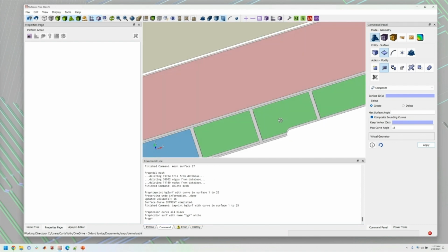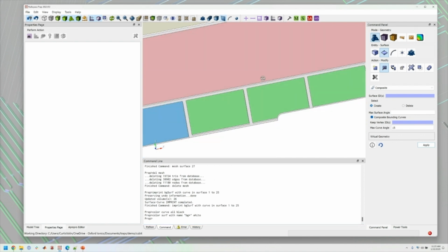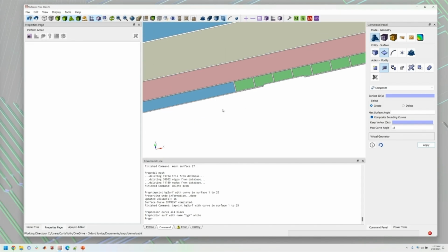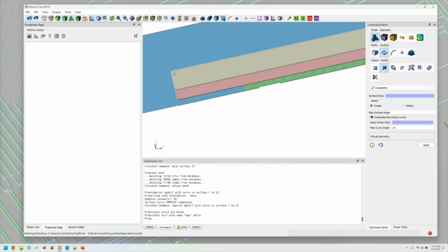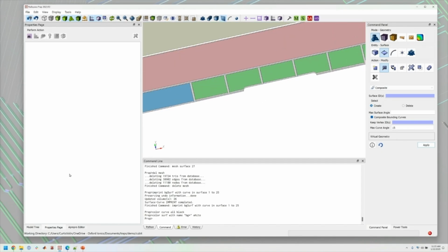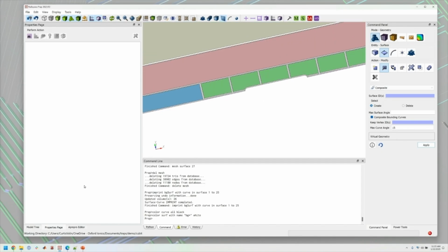And there you see that now the top metal structure is reproduced in this lower ground plane. Note that the ground plane is only underneath the portion of the trap that is near where the ions are. We don't need to have that ground plane out here. It's not going to affect the fields that are present in this part of the trap, and that removes metal that you don't need for the simulation.